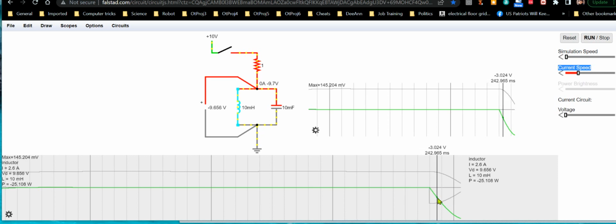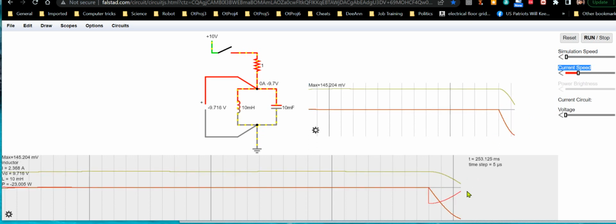So in this case, since you've got a capacitor hooked into it, the voltage across the capacitor keeps increasing as it eats charge, as it starts to charge up. But as a result, the inductor has to generate a slightly, an infinitesimally higher voltage than what the capacitor has across it. And it does that the whole time, right until it runs out of juice. It'll continue generating a slightly higher voltage even when it's got negligible energy stored in it. It'll keep doing that up until it has no energy left. And when it has no energy left, that means the capacitor is fully charged.